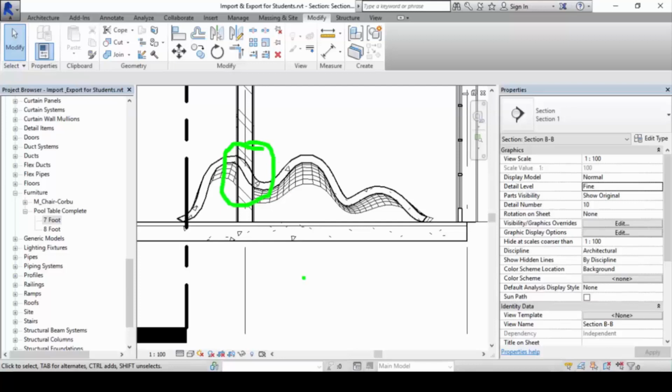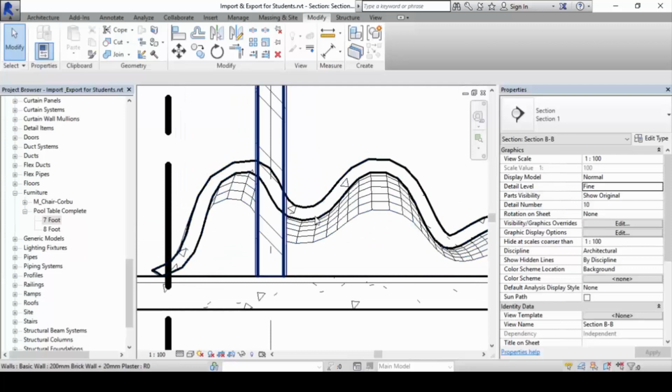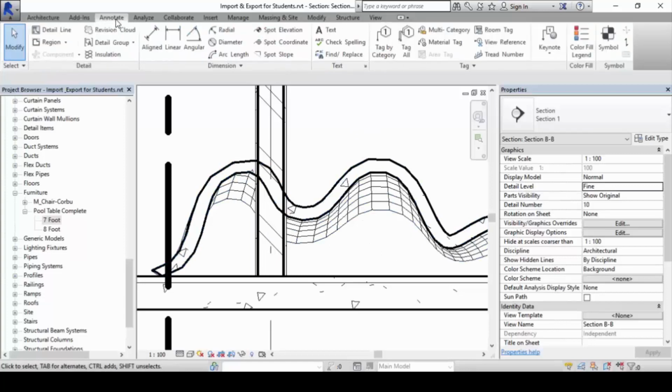In documentation and design presentation, this is an absolute no-no. But in 3D modeling, you want to be able to do that because you will save a lot of work. Rather than building two pieces, you just build one piece and let it cut through and stay that way. So in Revit, we will touch this portion up by using the liquid paper technique, to cut this off. How? We will click on Annotate. This is the part where we use 2D to touch up what is lacking in 3D. To model this part in 3D would have been very painful and difficult, but we can simply use 2D to touch up this portion.